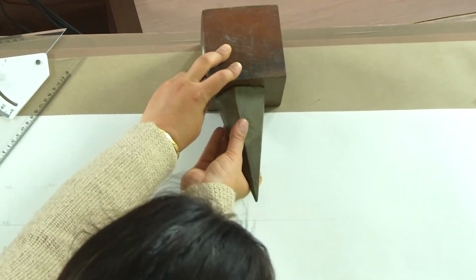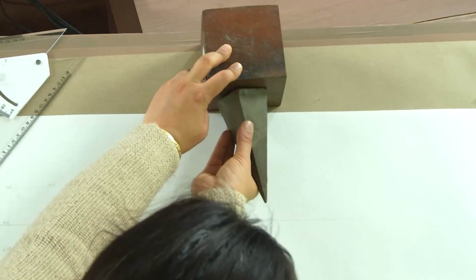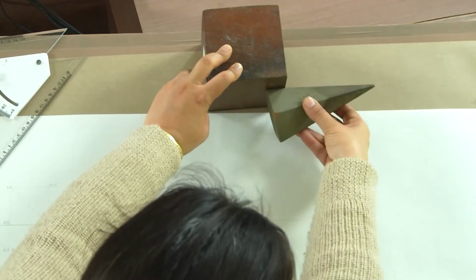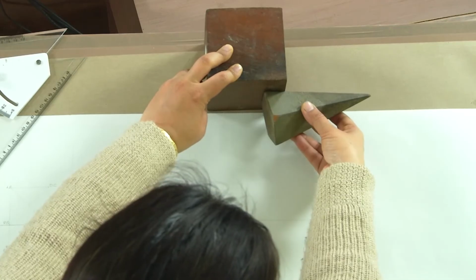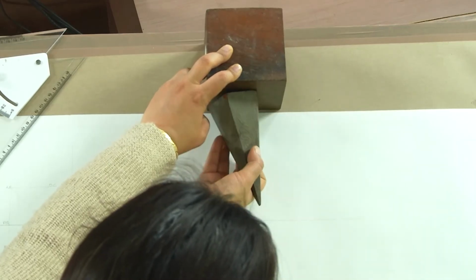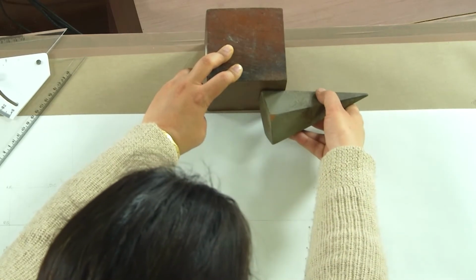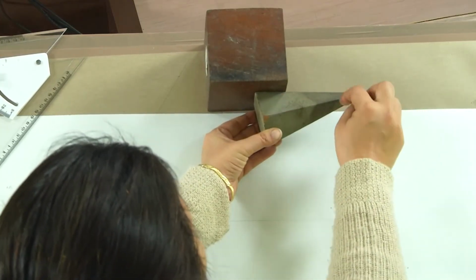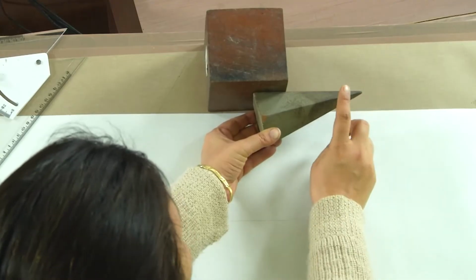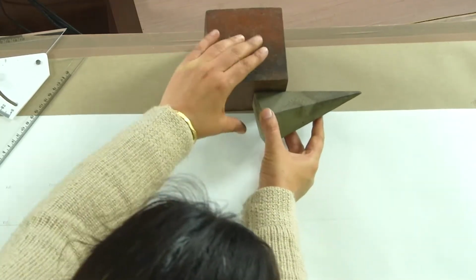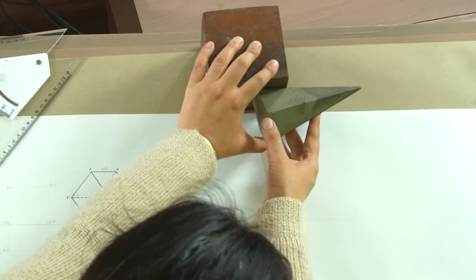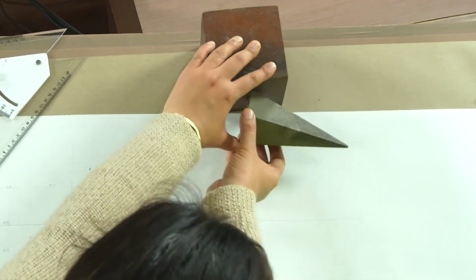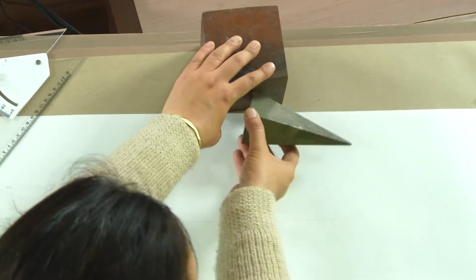So, we will have to incline it in such a manner that this axis now makes a certain angle with this. So, this is how we are going to incline. If you look at this, this axis is actually making a reverse angle equal to the angle of the cone here, and then we will draw the front view. So, that is one inclination, and the axis is still parallel to HP.